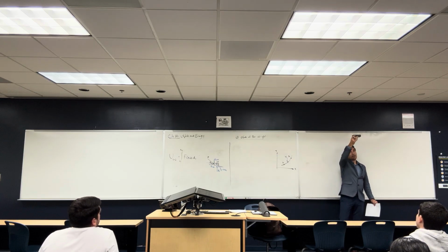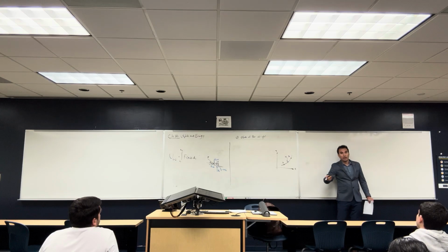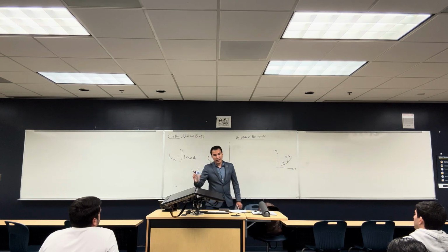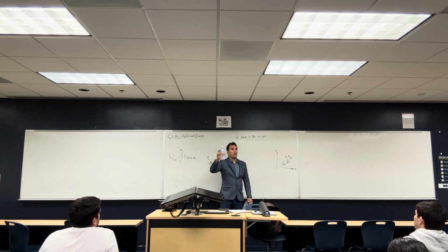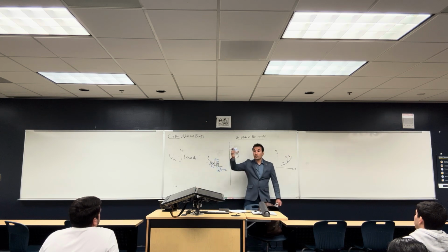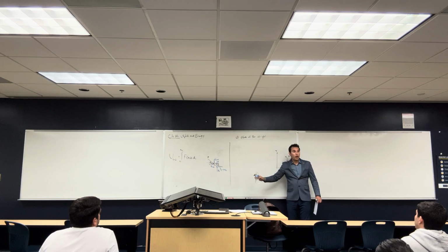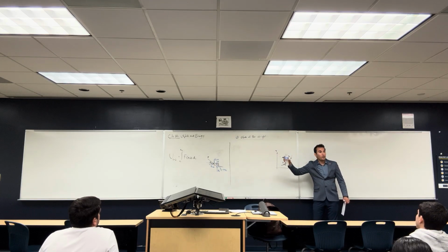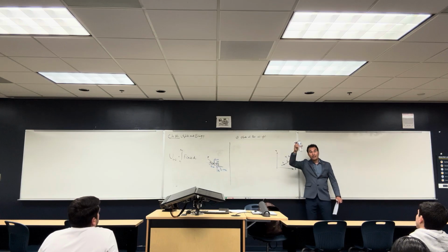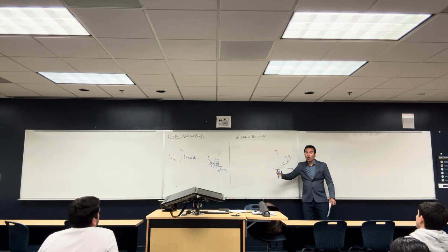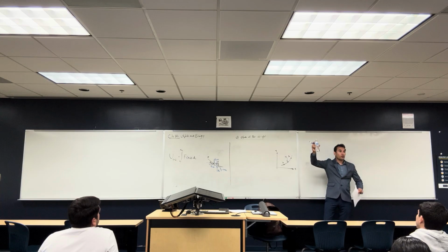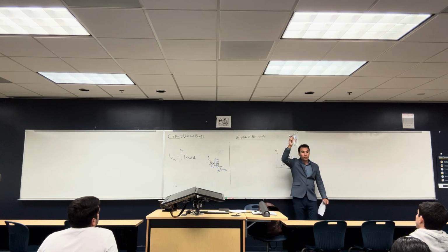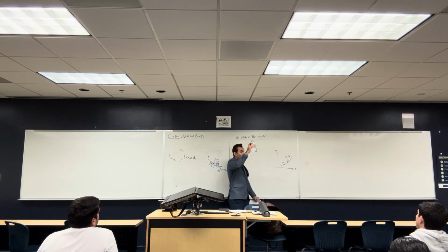But let's say my hand's here, and I grab the body like here. If it's a really heavy body, like my water bottle, it's hard for me to bring it up, but it's easy for me to bring it down, right? Because I'm coming down, that's a positive work. Why? Because the work of the weight is in the same direction as the weight, which is the gravity direction, so that's a positive work. But if you are trying to move the bottle up, you are trying to overcome the gravity, so the weight has a negative work.